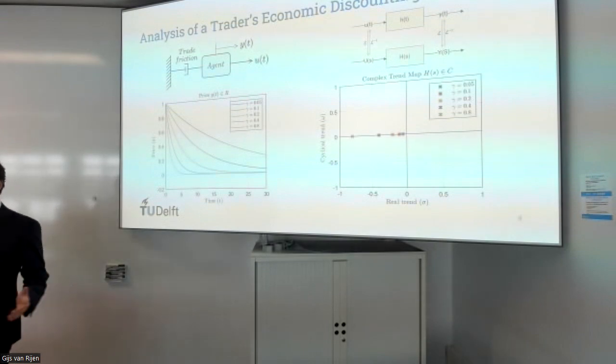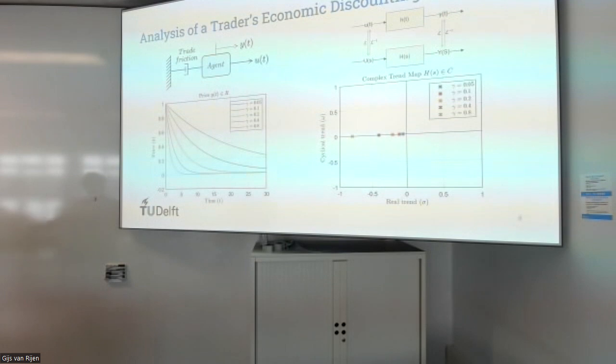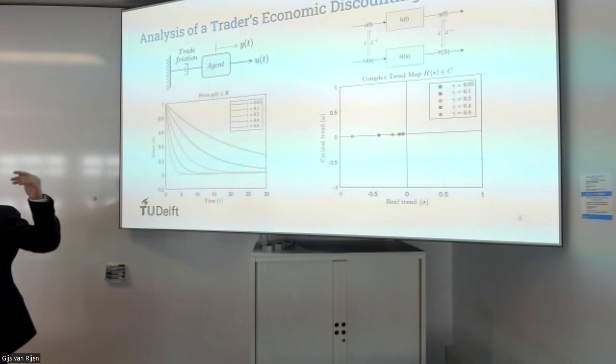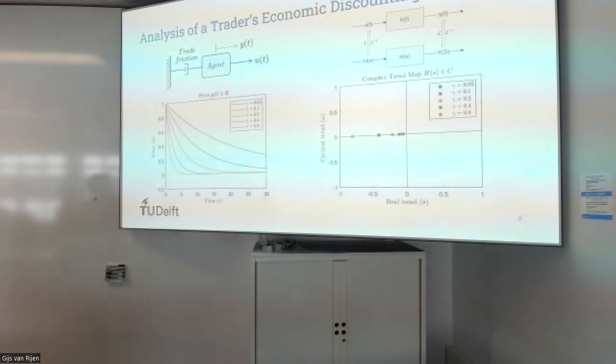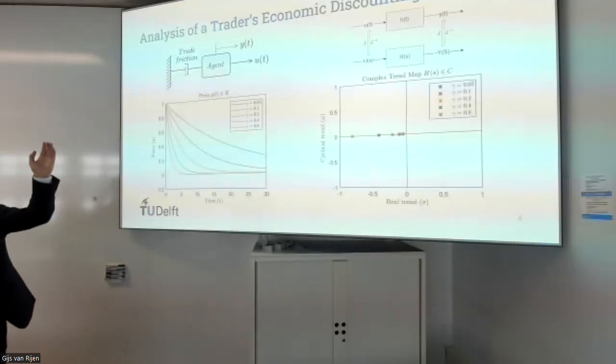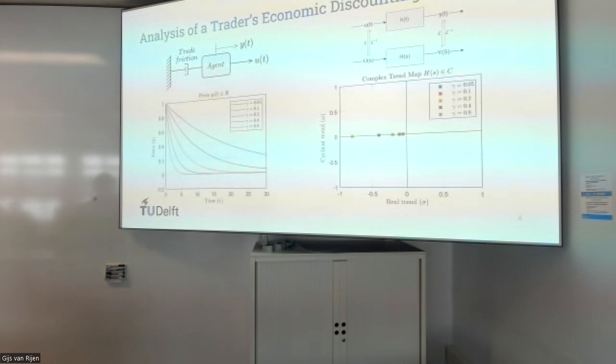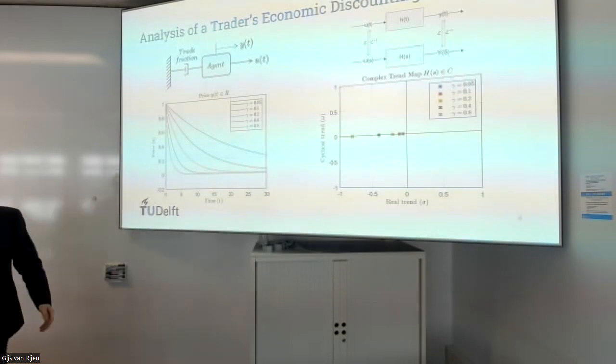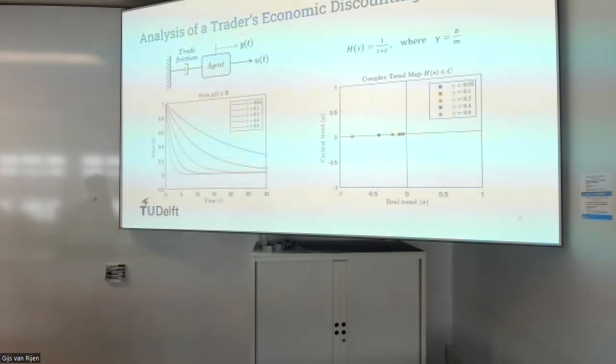Well, we can also look at the system in the frequency domain. And we do this by taking an input-output perspective, where U is the input and Y is the output. Then we can transform these signals to the Laplace domain, getting U of S and Y of S. Then dividing the output by the input, we find a transfer function, which is a representation of the system in the frequency domain.